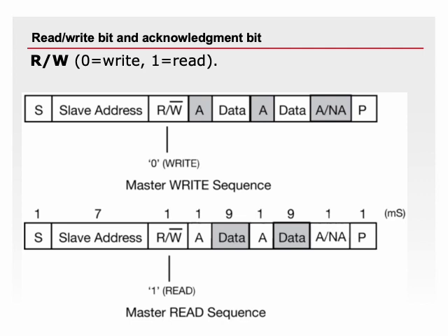After the address data, we have the read-write bit that is used by the master device to indicate whether it intends to read data from a slave device or write data to it. Just in short, in addressing mode, the master sends a 7-bit address of the slave device followed by the read-write bit as the 8th bit, becoming overall a byte.